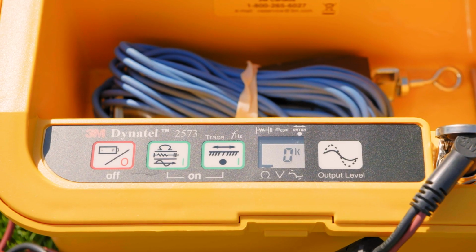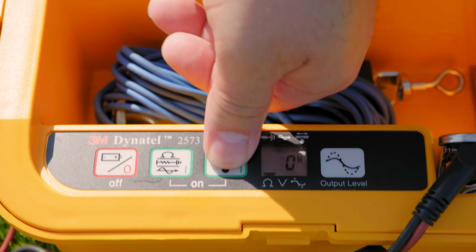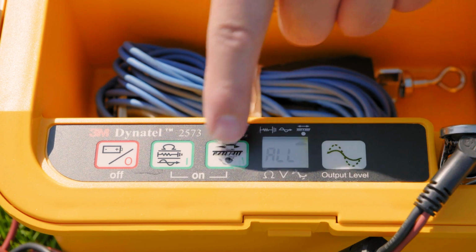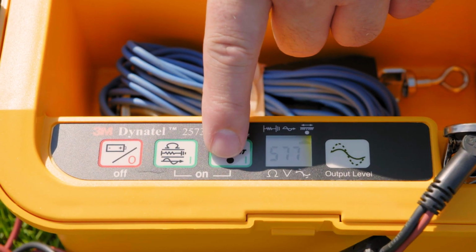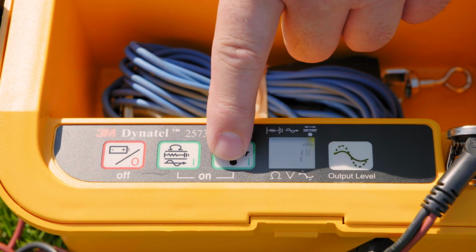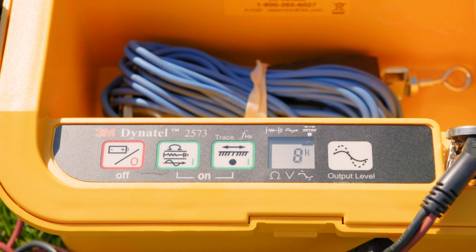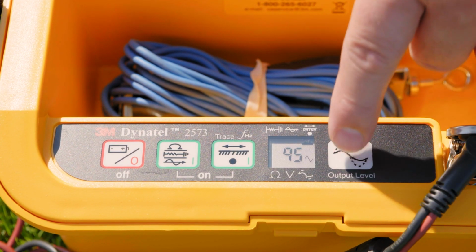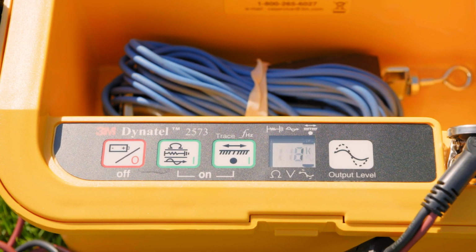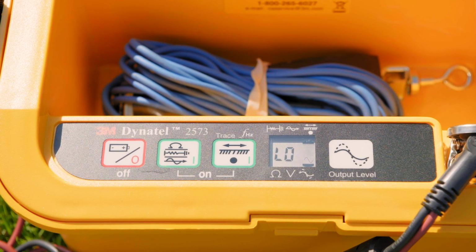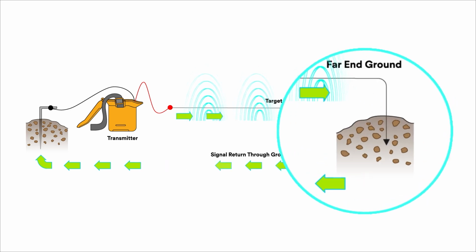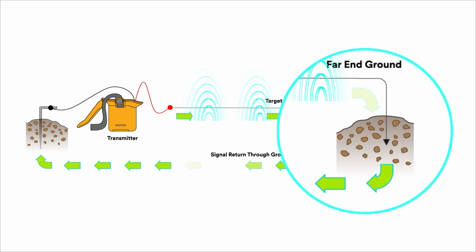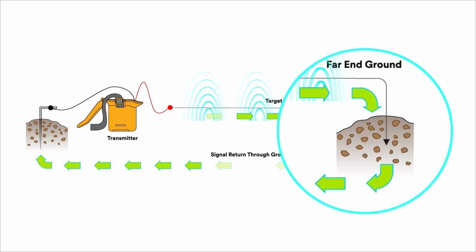When using the direct connect method, the transmitter current level will alternately flash with the selected frequency on the display. Make a mental note of the transmitter current level before you start locating the target path. To help verify the target path, compare this transmitter current level to the current measured by the receiver on a suspected target conductor. If low is flashing alternately with the frequency, the signal path circuit is incomplete or inadequate.